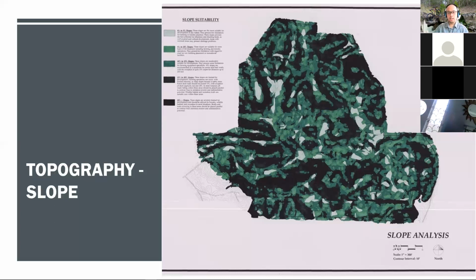On the other hand, sites that are essentially flat, which have less than 1% slope, may have very poor drainage, because if it's flat, then water won't be able to flow, or won't have a good runoff area.